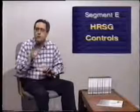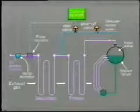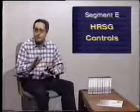Okay, so much for trips of the HRSG, but what about control? As we have already mentioned, the exit steam temperature is continuously monitored and controlled by injecting feed water into the de-superheater. Both the superheater and reheater temperatures are controlled in this manner. Maintenance of correct temperature is very important.